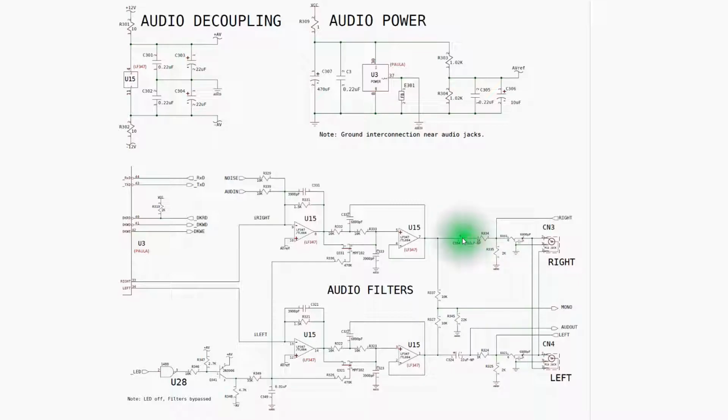We get down here and look at this symbol here. The symbol's drawn as a polarized capacitor, but there's this little dash NP off here. And that dash NP says this is really meant to be a non-polarized capacitor. And that's ultimately non-polarized because this signal here can be swinging up towards plus 12 and minus 12 or whatever the voltage it swings. It can swing around the ground reference.